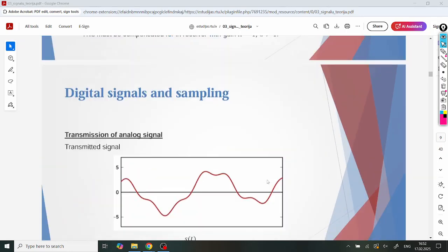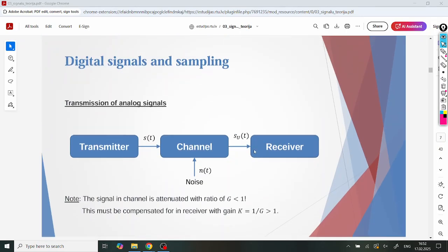realize that now at this point, the weakened and noisy signal gets to the receiver, to the antenna, and an amplifier that is going to boost power by adding gain, not only to the signal, essentially, that it sees, but the problem is your signal includes noise as well, which means noise is also going to get boosted.